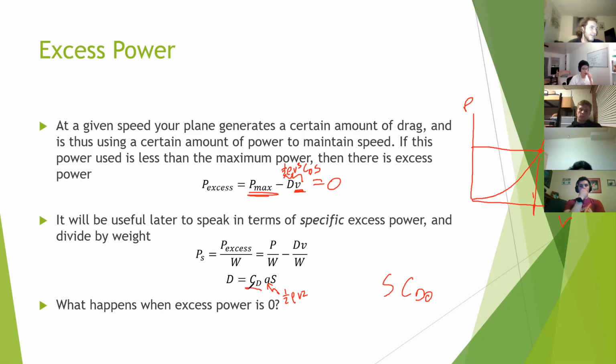You can calculate the induced drag coefficient using the drag polar that we already talked about. You also need to assume the Oswald efficiency and aspect ratio for the drag calcs. But other than that, you can just set a power and solve for your flight speed.